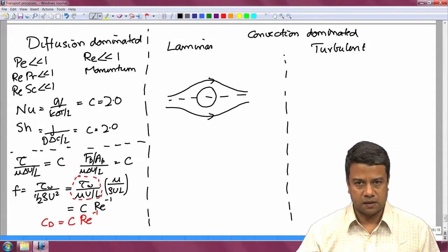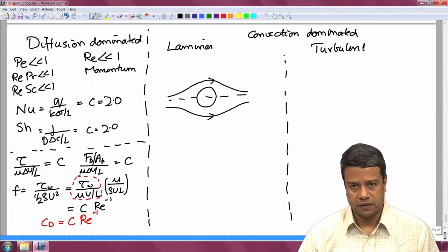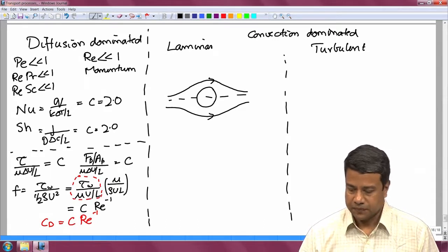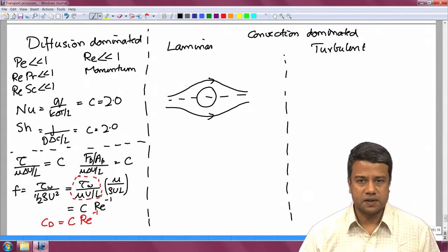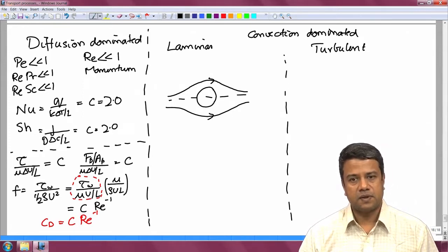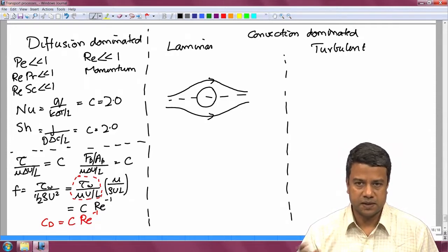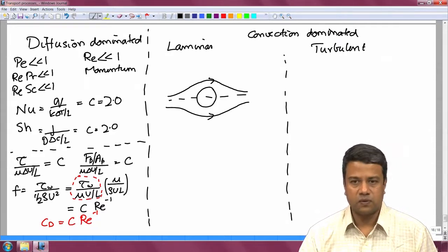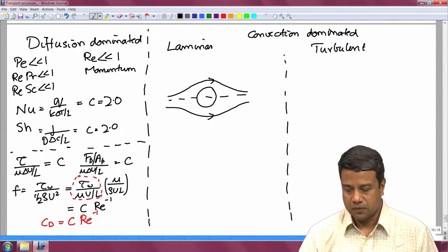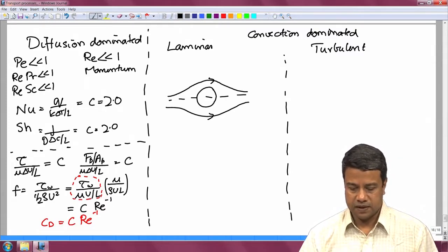Take the droplet that was drying in the spray dryer, for example. Diffusion would be dominant. When convection is dominant, there is material that is diffusing out of the surface. At the same time, that material is also being swept by the fluid flow past that surface. So, there are two effects happening. What does it mean when you say that convection is dominant?